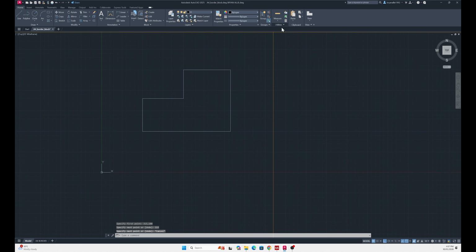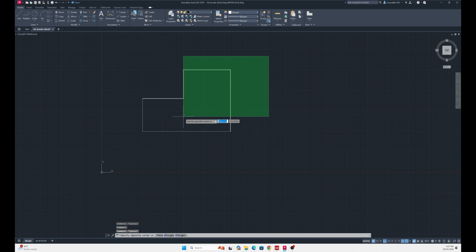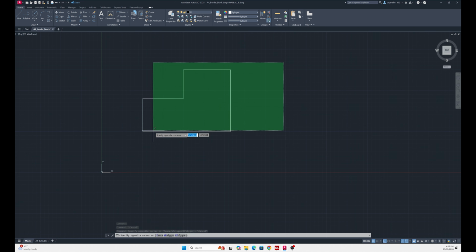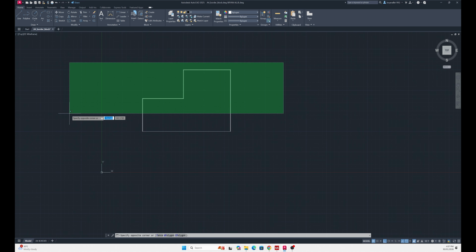And if you want to double check anything, you can just go to measure quick, especially good when you do the rectangular geometries. So it's 150 by 215, which is great. And as you can see here, if you want to join it together, see how it's all in separate entities, you can just left click, but swing the cursor to the left so you get the green.